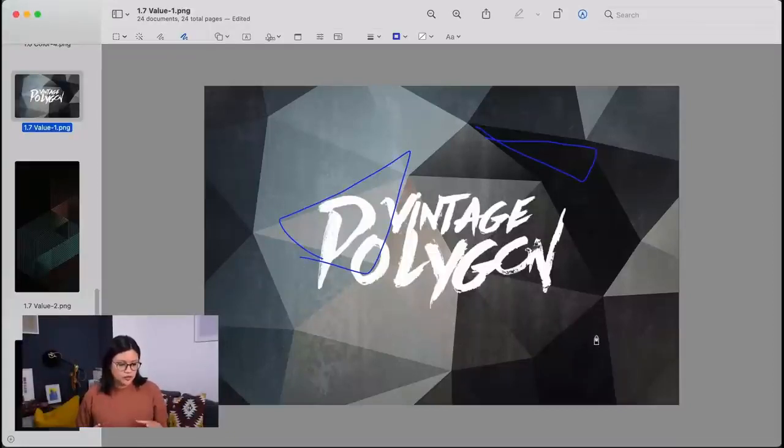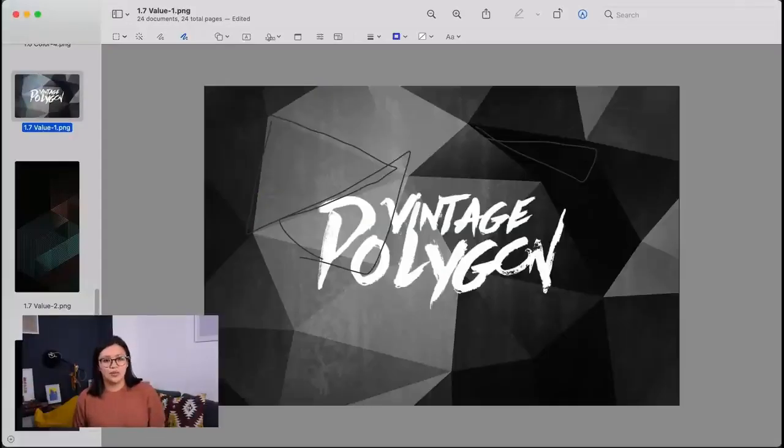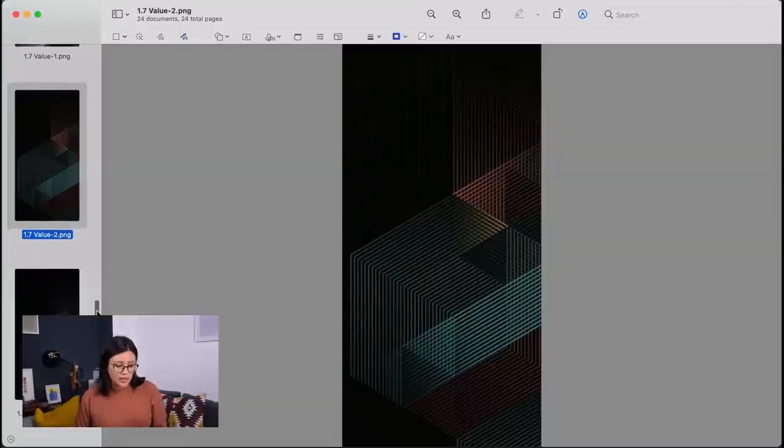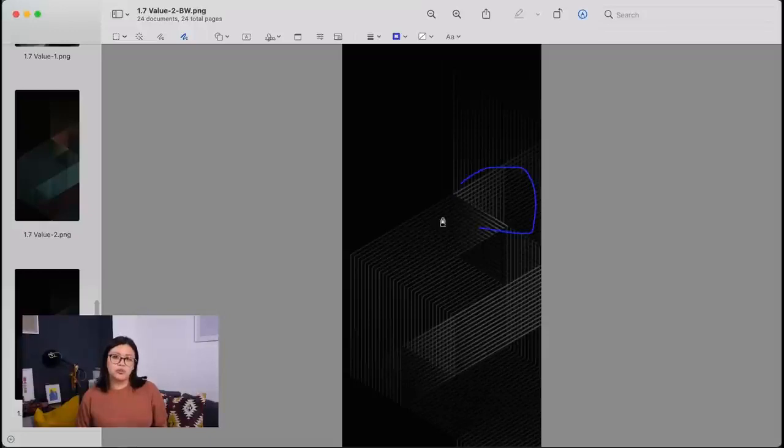In InDesign, using different tonal values can create, again, contrast, but also the illusion of movement by overlapping multiple elements with different values. So again, if we turn this image into grayscale, we can see a high contrast between light and dark. On this particular example, if we switch the image again into black and white, we can see that the value of the orange and the blue are the same. So while these two colors are contrasting, the values avoid making them as contrasting as they could be. So that's a reason why the design can look flat sometimes.